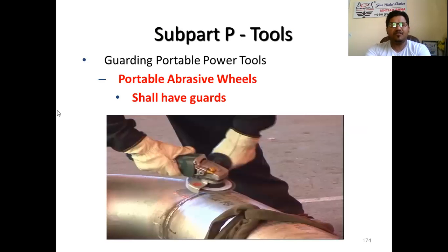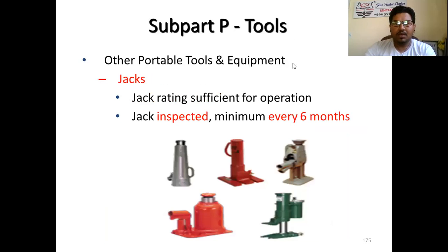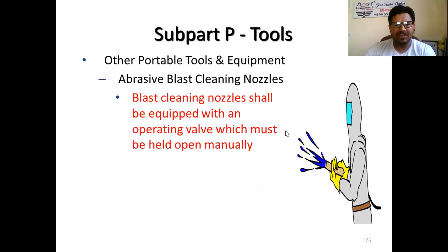Make sure you have guarding related to portable abrasive wheels. They must also be guarded. And there are some jacks, like the rating sufficient for operation, and jack inspection, minimum 6 months as per OSHA.